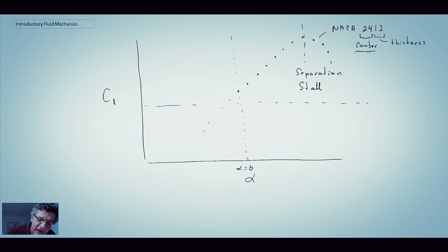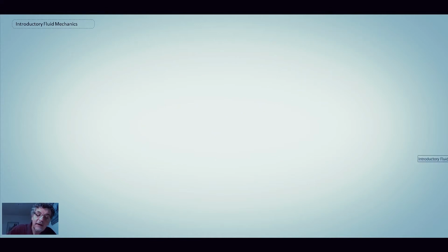And then it would go down, and if you're dealing with something like a 0012 or 0015, then we would pass through 0, so that would be a symmetric airfoil. So that is how the data is plotted, and then there will also be moments. Sometimes they'll have moments about the quarter chord, and there will also be drag, so you'll get the drag characteristics for the airfoil.